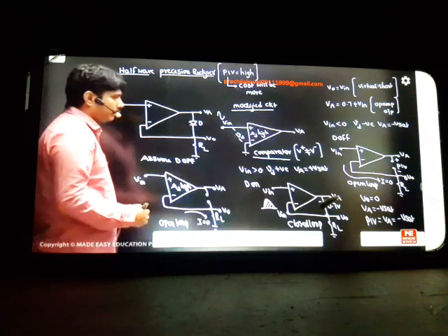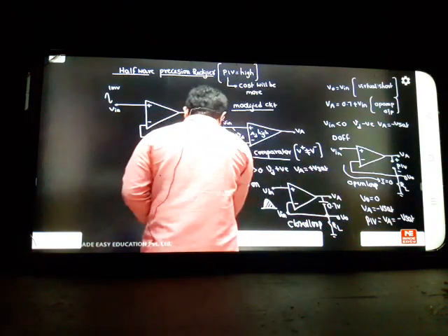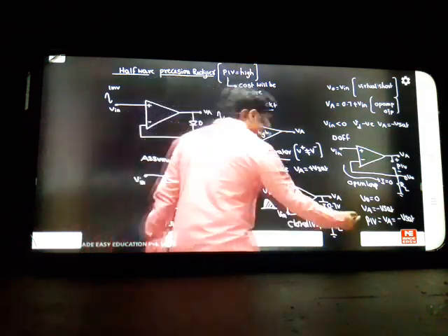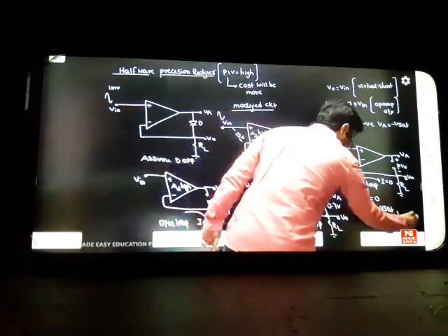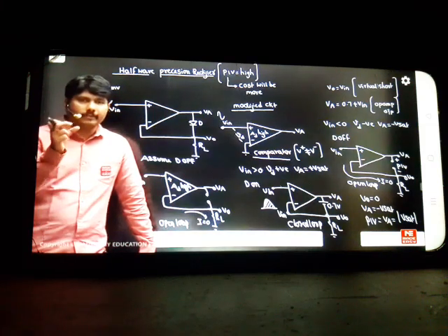But PIV is generally stated magnitude wise. In place of writing signs there, better to show the magnitude answer. So PIV, we are getting V saturation. So that is the meaning of what I am telling in the class. When the diode gets off, the complete saturation voltage is going across the diode.